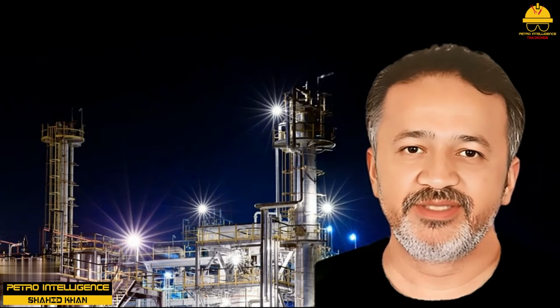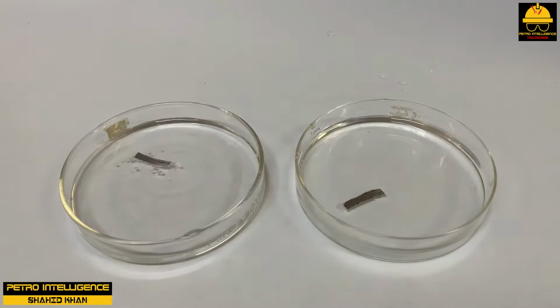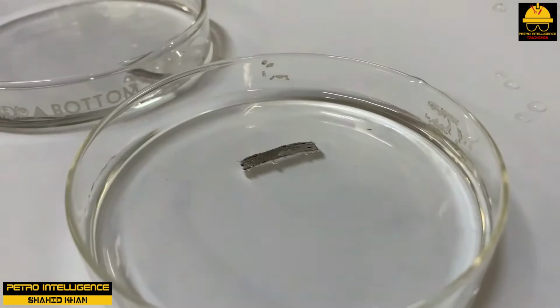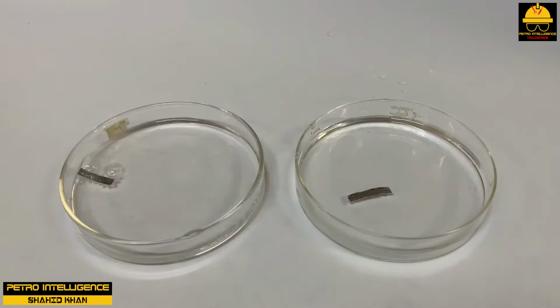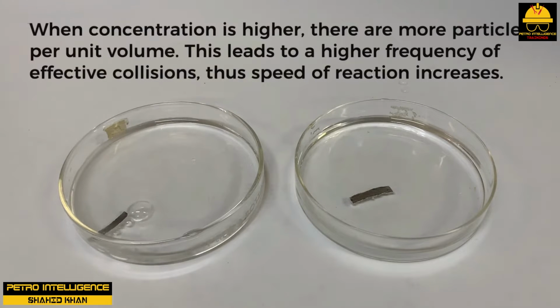Concentration of reactants. The concentration of reactants in the reactor has a major effect on how fast the reaction will take place, what products will be produced, and how much heat will have to be added to or taken away from the reaction. We generalize here for the sake of simplicity and say that for most reactions, the higher the concentration of reactants, the faster the reaction and thus the more heat that is generated or needed.